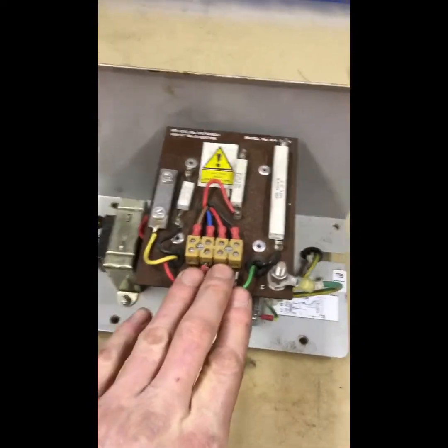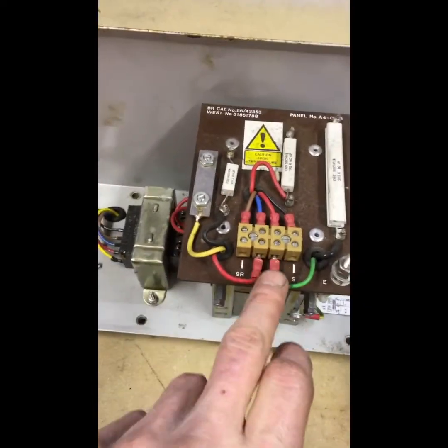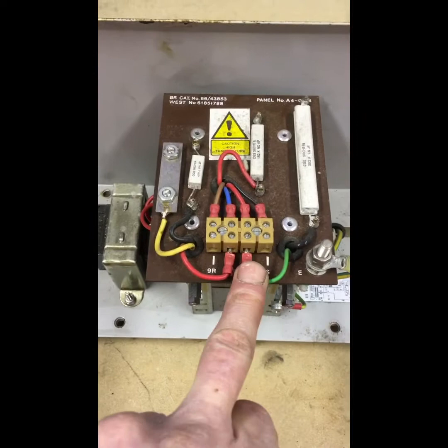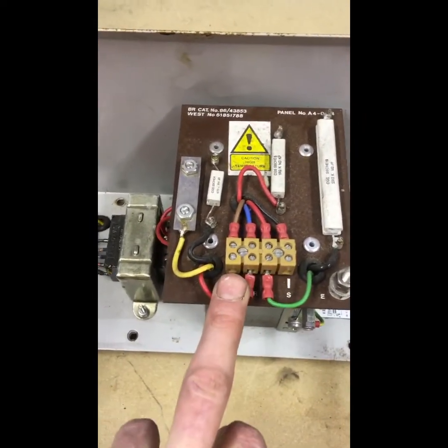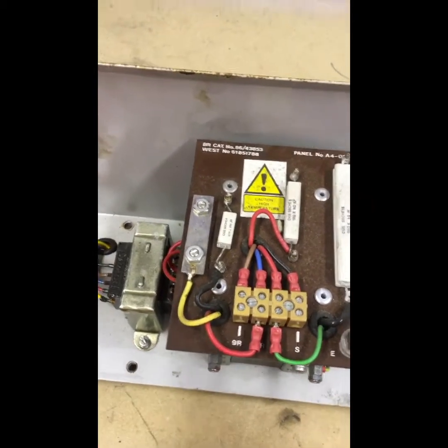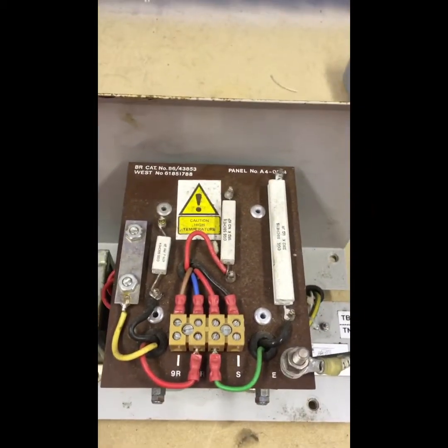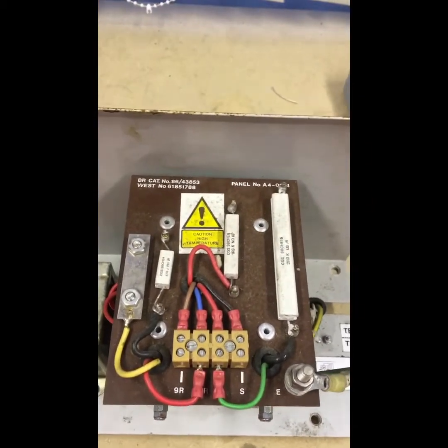So if you're going to set these up on the track, on a long track, you'd set it to the long setting. If it's quite a short track, you set it to the short setting. And obviously match your relays for 9 and 20 ohm resistances, which you should be able to find out quite easily if you look at your relay coil. It should be stamped there as an R number.